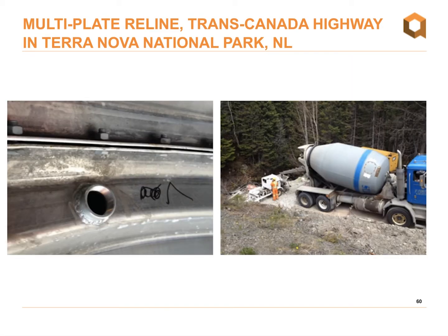So once all the rings were fully assembled and the bolts were torqued, the specified torque on these being between 115 and 135 foot-pounds, the grouting was then completed using a portable concrete pump. The grout mixture was freely flowing with an approximate 6-inch slump. It was placed in 3 uniform lifts along both sides of the pipe while ensuring the design diameter was maintained.